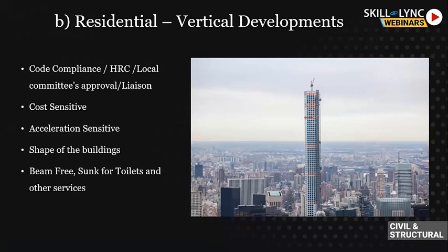Then there are the huge foundations that we look at at the base of these tall buildings, around 3 to 3.5 meters in depth. You imagine the height of one residential floor going into the foundation. So the amount of concrete and steel there, and also the challenges because of the mass concreting for these foundations. If you look at it in perspective, it's the foundation of two average human heights. So two people standing over one another is actually the depth of the foundation.